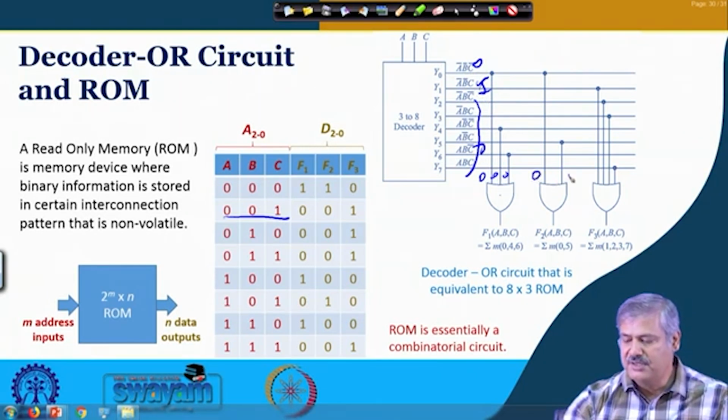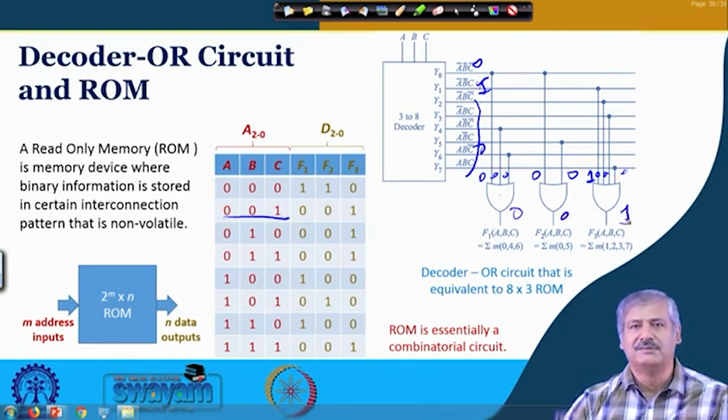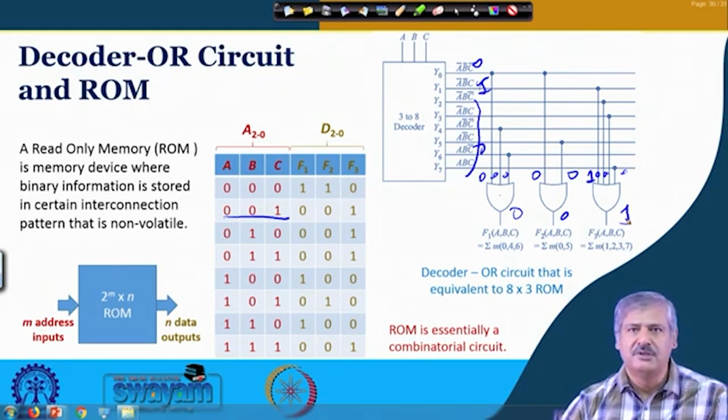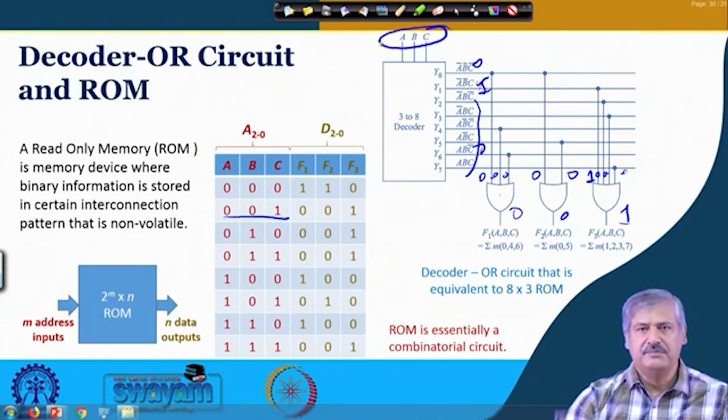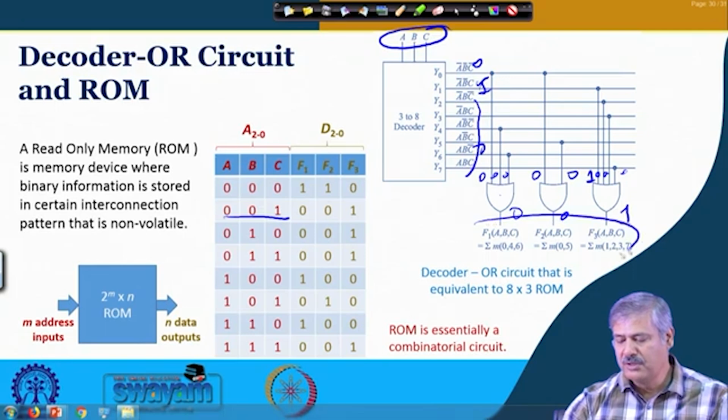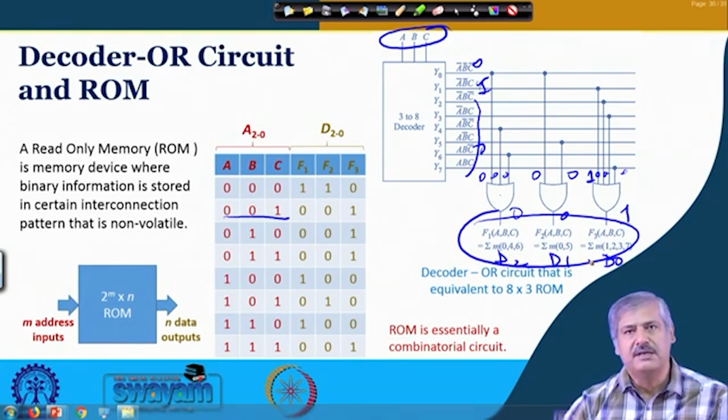Similarly, over this is 0, this is 0. Here this particular one is 1 and the rest are all 0. Okay. So this output will be giving you 0, 0, 1. Is it fine? Is it understood? Right. So you place the location address bits, and at the output you will get, the way we have configured it, D2, D1 and D0 by this arrangement. Is it fine?